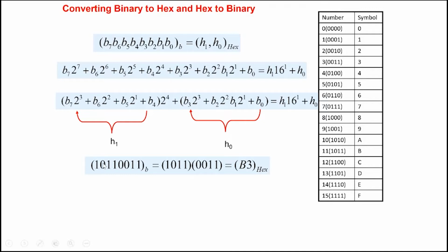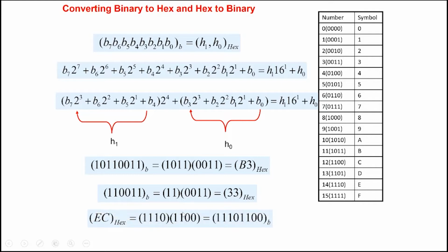And so instead of writing this 8-bit number like this here, we can write it like B3 hex here. Whenever you use A, B, C, D and all that, it's understood that B3 is hex here. And converting it back, okay, so once more, what about this binary number? How do we convert it into hex? Starting from the least significant bit, take the first 4. So group them, 0011, and the next one is 11. So this is represented as 33 hex here, right?